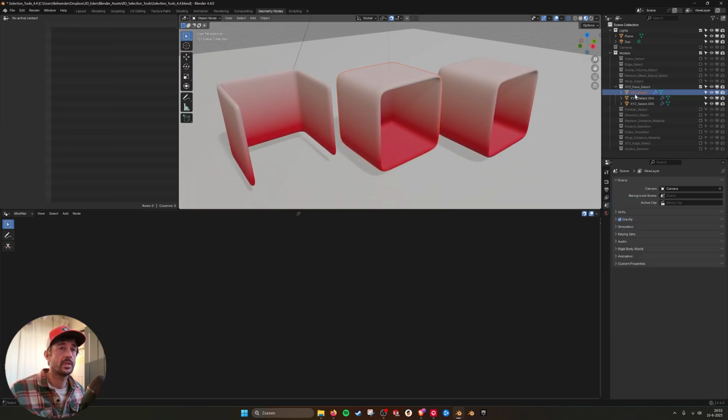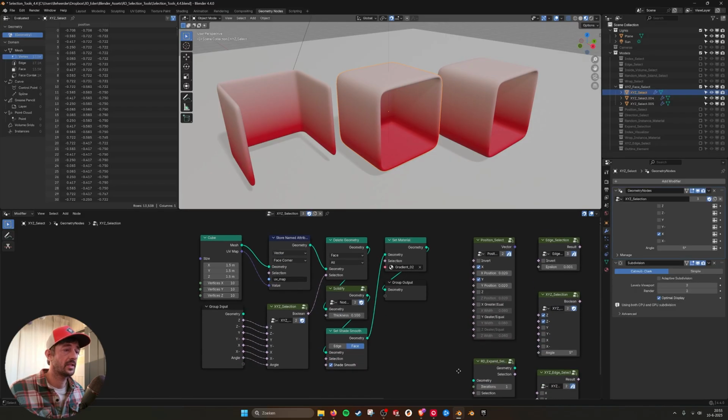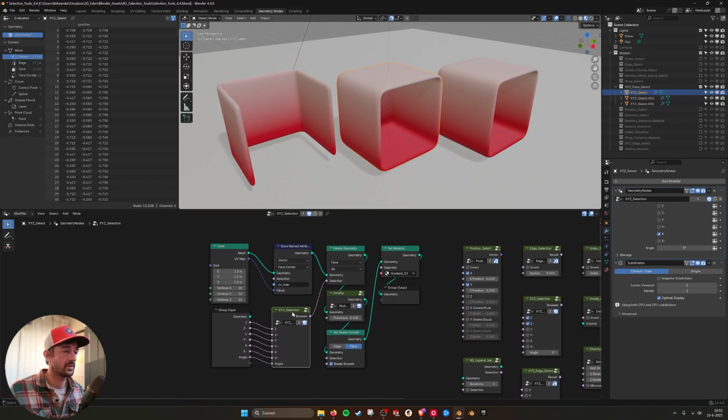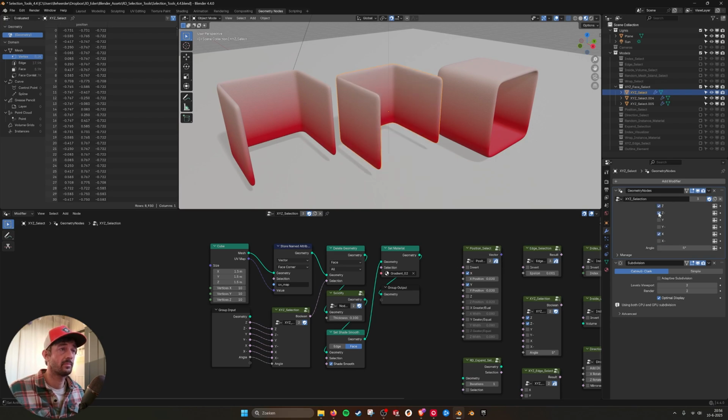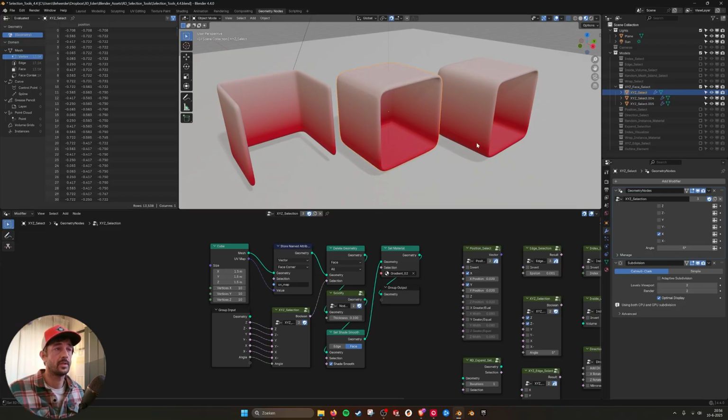The next one is the XYZ phase select, and that's just an XYZ. You can just check the boxes if you want to keep the Z or the -Z or the Y, minus Y, etc. So here you can see this one, I have only the X removed. When I do the Z, it removes the top. When I do the Z, minus Z, it will remove the bottom. And this way you can just delete faces of your model.